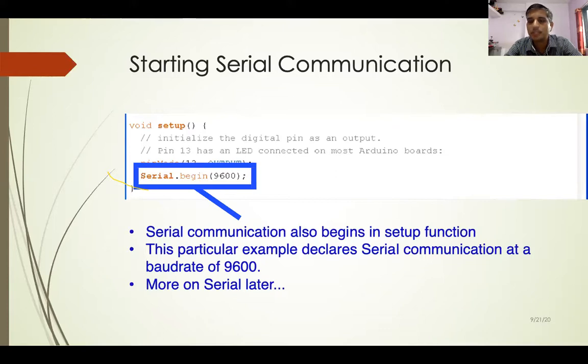If there is only a single line available for only transmission purpose, there is no reception line available, then that type of serial communication is called as, can anybody answer me? It's called one-way communication. The sender is only sending, the receiver is only receiving. The receiver cannot send data, or the sender cannot receive data. So that type of serial communication is called simplex communication, just like your television set.